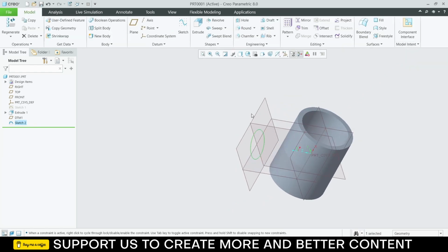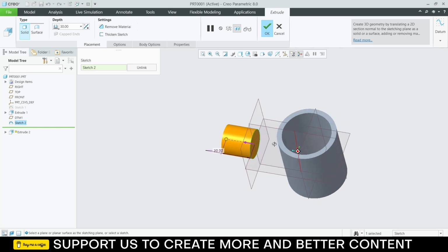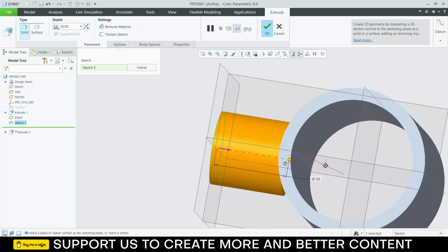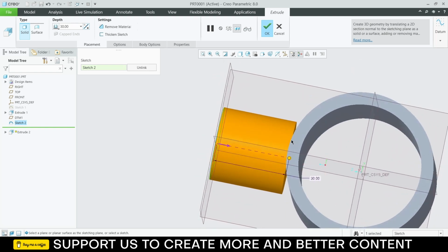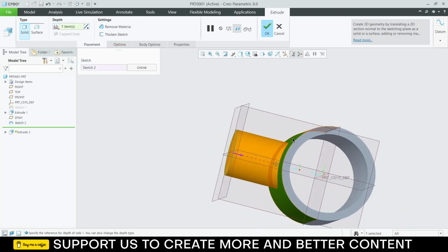Now watch carefully what I will do. Click on extrude. Now I want to extrude up to this surface, not outside, not inside. So how should I approach? Some people will think, hey, click the reverse direction and extrude it. But the issue is the curved part. If you move too much forward, then this flat surface will still be there. But if you move less, then again there is another issue. So what you will do, click here, click on to reference. Now select this face. Notice it extrudes only up to the surface, so it is quite handy.